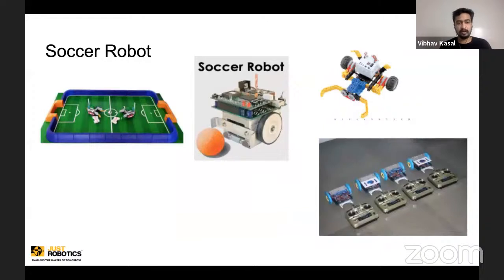Even though you think the robot has more grip and thread, the contact surface with a harder surface is not effective. So the wheel is touching only at 1 or 2 points. One small experiment that I usually ask kids to do when they're choosing a wheel is to paint over the wheel and ask them to stamp it over a paper. So you will see the wheel track print. Then you can see how much contact area that is. So you have to know what the contact area is and how much friction it can get.